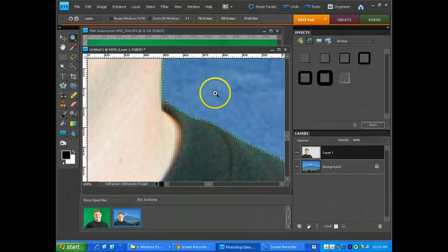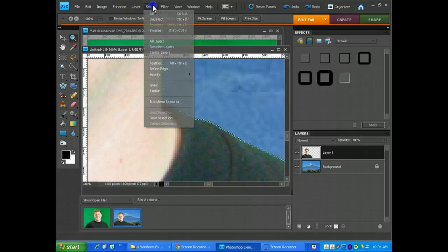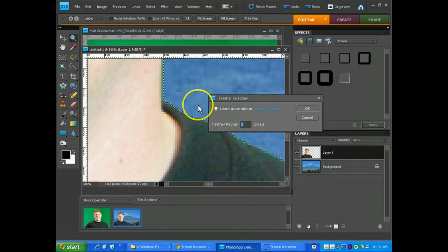We've selected these pixels, which are empty, on this layer. We are going to expand the selection slightly by using Select and Feather. I'm going to feather this by 2 pixels because I have a fairly high resolution picture. And what it will do is blur this line by 2 pixels, 1, 2, and it'll start to take a little bit of him away, but more likely it's going to make things look like they blend.